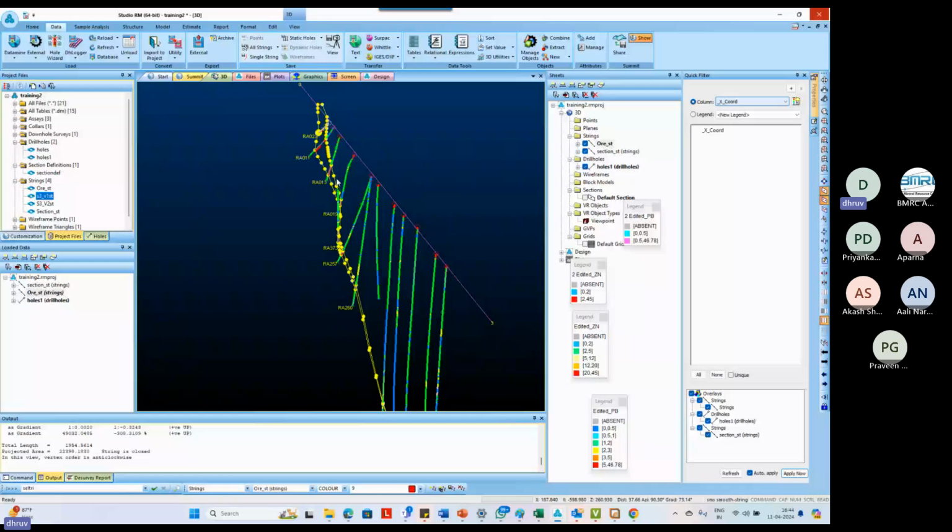you need to remove the crossovers while creating the wireframes, and crossovers are generated while these triangles are made. So when there is some overlapping of triangles, or some point goes into the other side, into another section, these problems will rise with the rise in the number of points. So it is better to keep it simple. Of course, with an increase of points, the wireframe looks smoother and more beautiful, but it creates a lot of problems, mainly in cases where there is correlation.